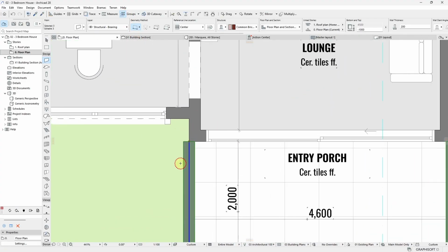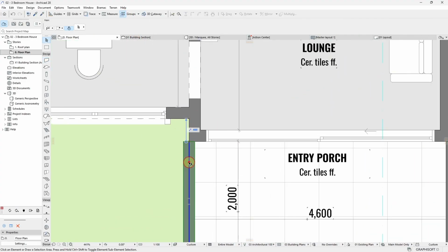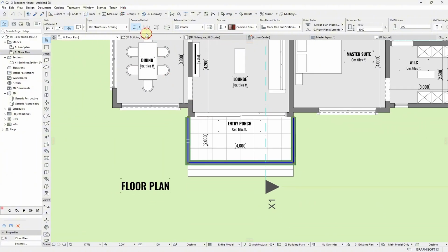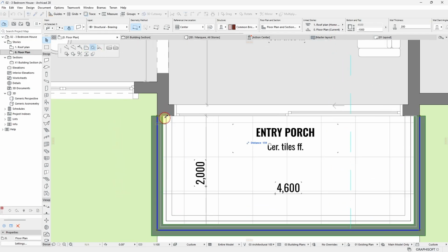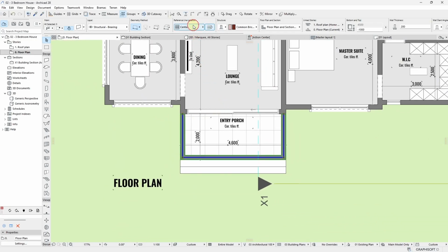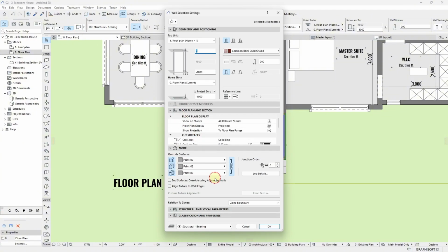And this wall is actually going to act as our beam. Like I told you, I don't need to put a beam when I know the final finish will just be paint. So I'm just going to make this a beam, and I give it a height, and I change the height from -1000 to 2.6, because that's where our beam level is. No, actually our beam level is supposed to be at 2.9, because we are using what?